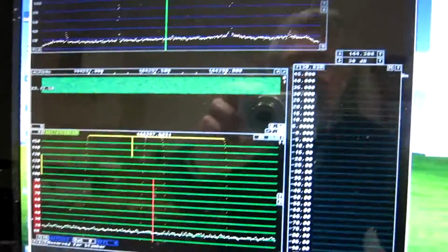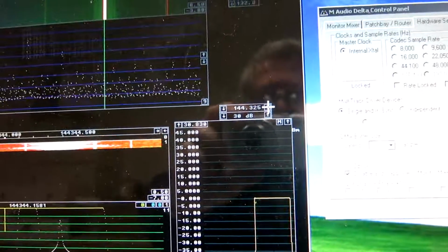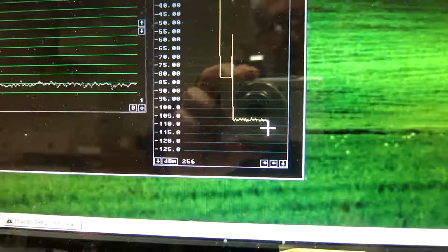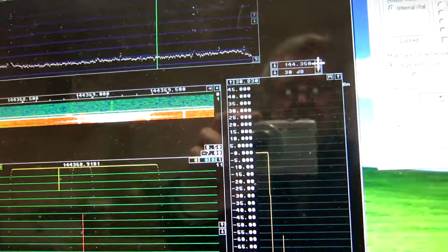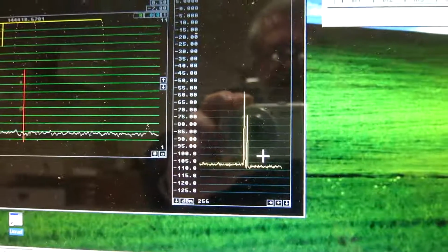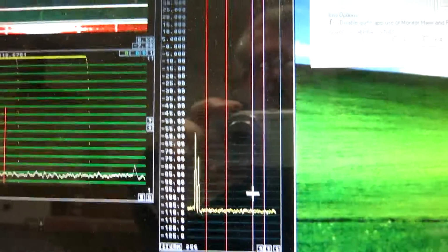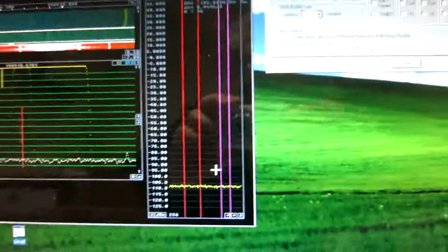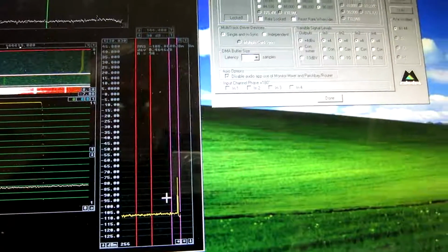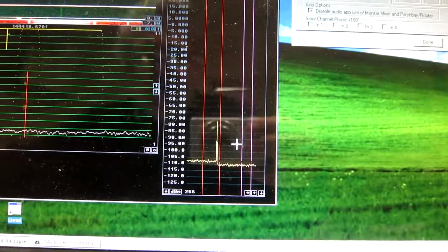And then I click on the signal again here, and then I step 50 kilohertz away. And then the noise floor is minus 106. And 50 more. This is at the 100 kilohertz separation. I can see the noise floor at minus 108. And now I switch off the 28 megahertz signal. And very little happens to the noise floor, so it is no longer dominated by reciprocal mixing.